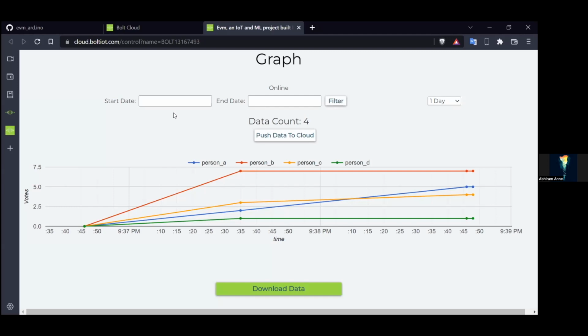There is one thing called Bolt Duino. In that, the Bolt module and an Arduino chip, the Mega chip, are built in, so you can use it like a combo of Bolt and Arduino. So you have more pins and more flexibility. Still, if you want to access more pins, you have to use UART. The Bolt module there also provides only the standard 5 GPIO pins, and the rest are normal Arduino pins. So you don't have to separately purchase an Arduino and a Bolt. Both are embedded together and connected through UART.